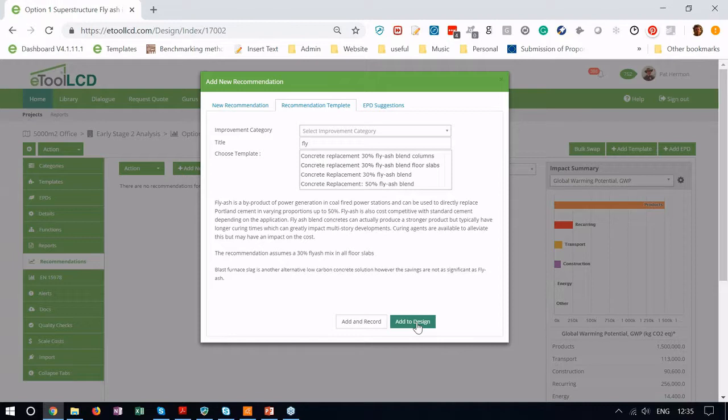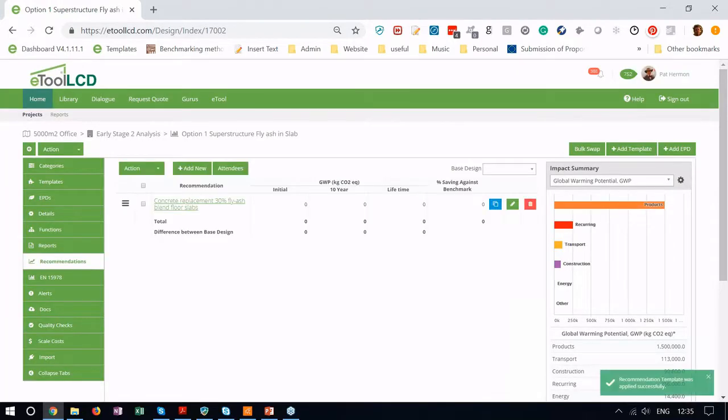I was at a conference yesterday and somebody had got a 70% content concrete, this was blast furnace slag rather than fly ash, and they were also actually offsetting the 30% Portland cement by purchasing offsets. So they were claiming a zero carbon concrete there, which was very interesting. Great that they've got that higher percentage in terms of concrete with the same structural and setting times, etc., as normal concrete. Sounded more pricey, 5–10% more expensive, but an interesting one nonetheless.